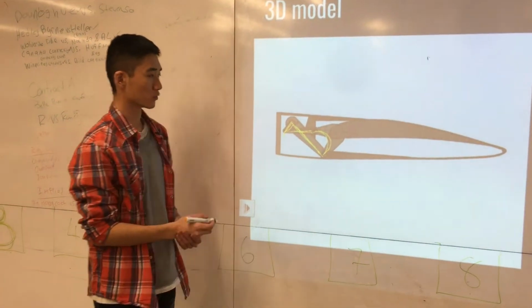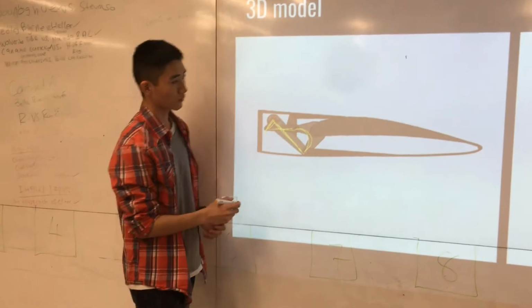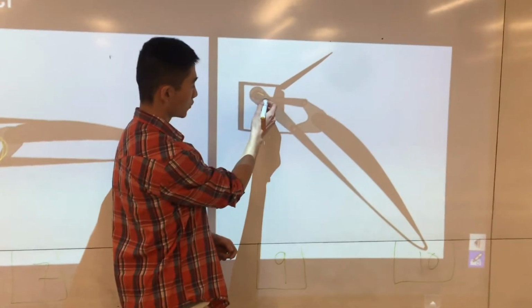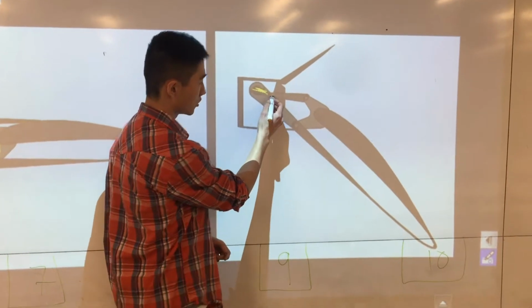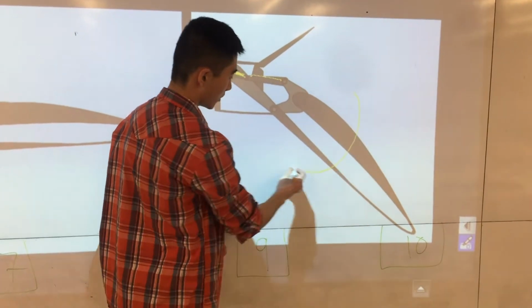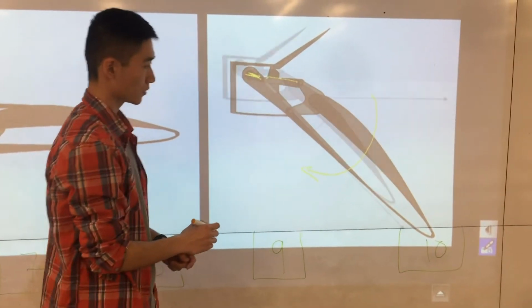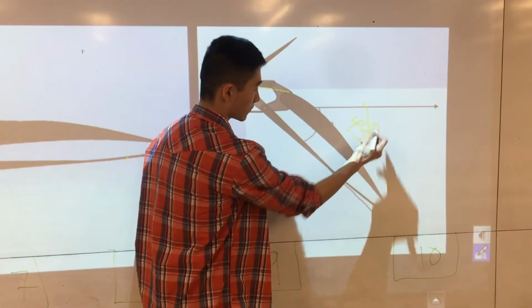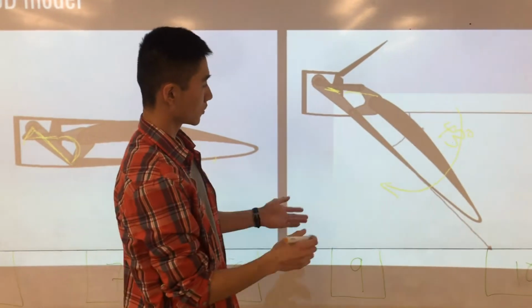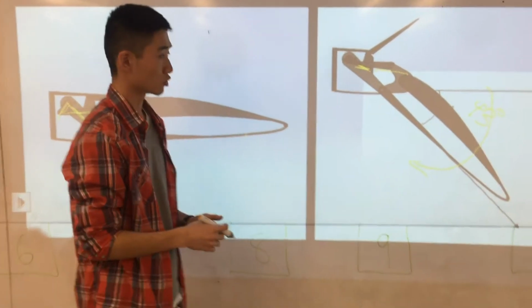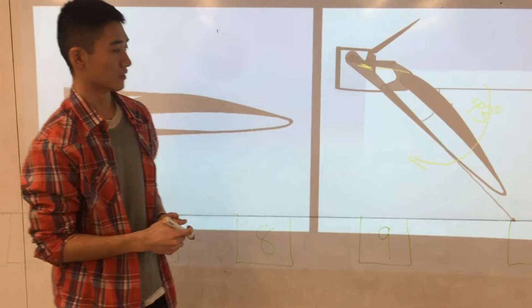Now these 4 bars will function first by rotating the motor arm. By rotating the motor arm, it will push the second linkage, which will then push the wing flaps down, allowing an exact 43 degree angle to be achieved of the wing flap. Doing so will shape the wings into a new form that allows more drag, slowing down the plane, and achieving its purpose.